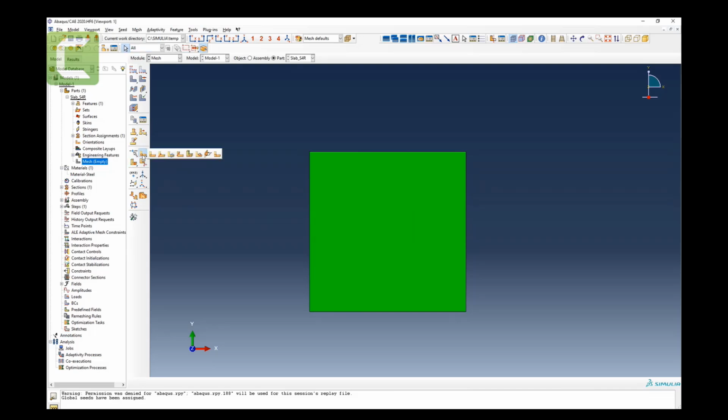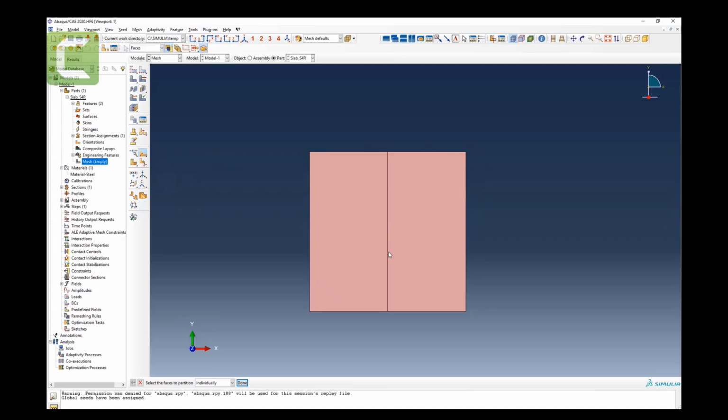We can do it here. These ones, partition cells using part between 2 points. So that's all good. Select the start point. We can do this start point and finish at this point and create partitions. So it will create this line where we're going to make our points.